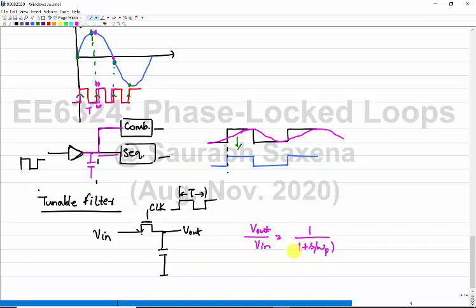I think in your analog course or some higher level course, you will learn about the switched capacitor circuit, where depending on the clock frequency at which you switch the MOSFET on or off, you can change the filter bandwidth. There you require a proper clock period, because your filter bandwidth becomes a function of the period.